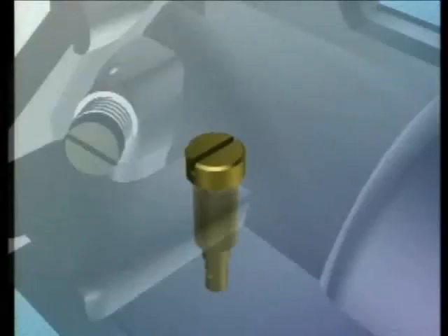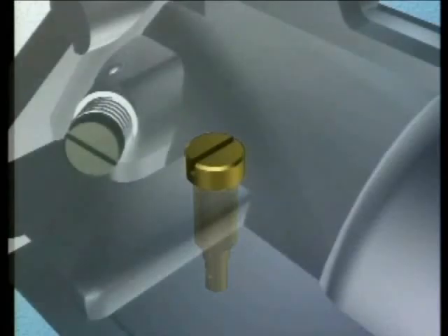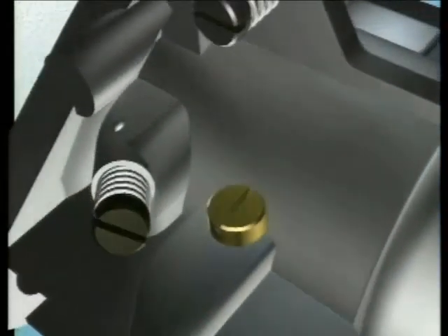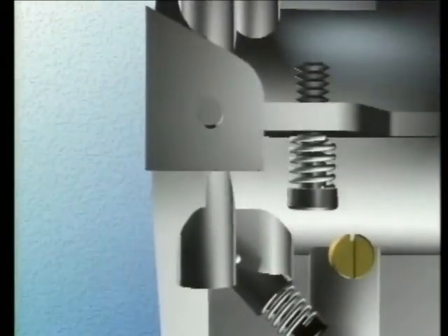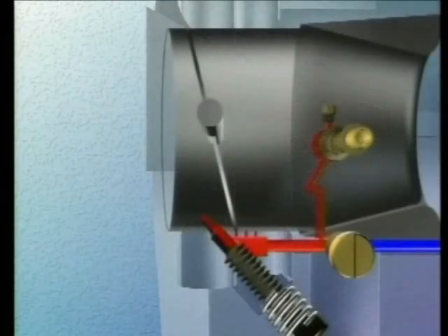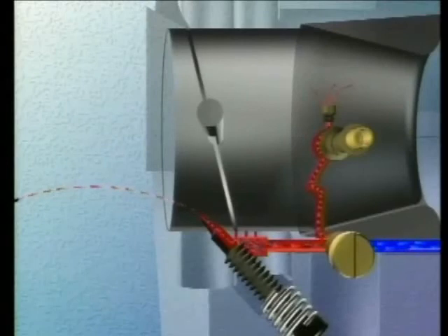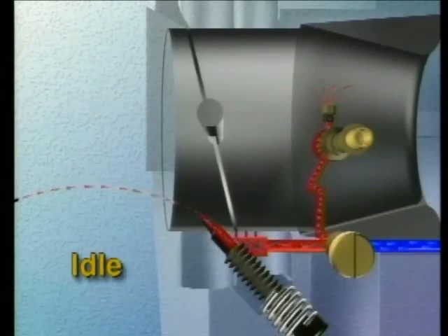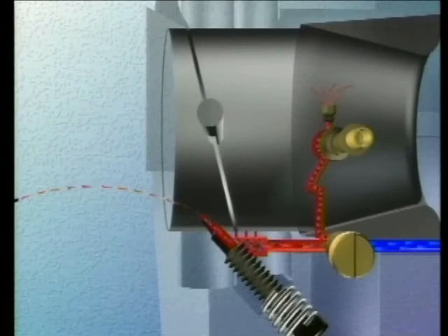Now, let's take a look at another aspect of today's modern carburetors. In systems which still feature an idle circuit, you'll often find a pilot jet, a fixed jet for the fuel introduced into the idle circuit and into the transitional hole reservoir. The pilot jet restricts the fuel coming up from the bowl into the idle circuit as engine conditions change. At idle, the fuel delivery is not restricted very much. That's because a very small amount of fuel is needed to maintain idle speed.